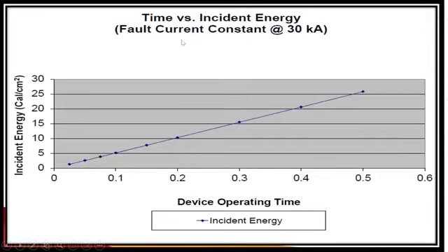But over a period of time, after 5 years, the equipment was not maintained correctly, and due to poor maintenance, the device clearance time and the operation time of that particular equipment increased from 0.1 to 0.4, 0.5, or 0.6.